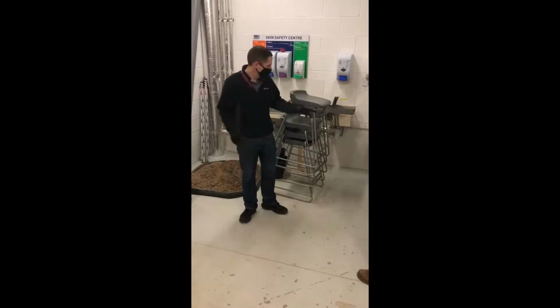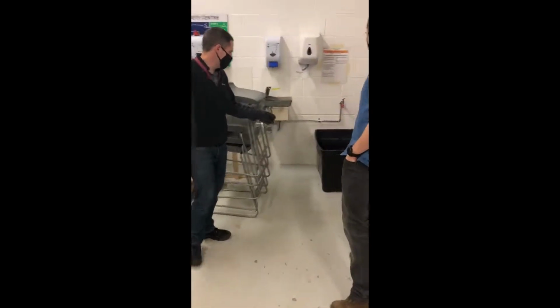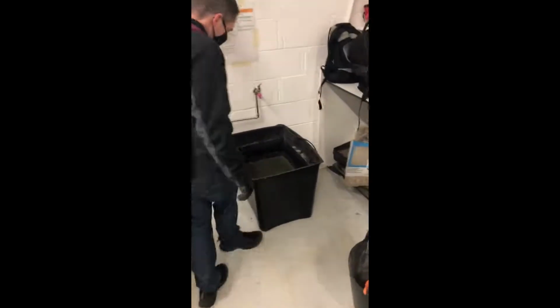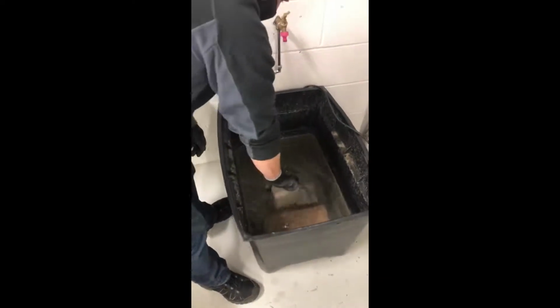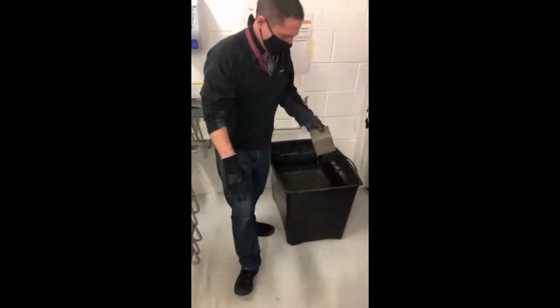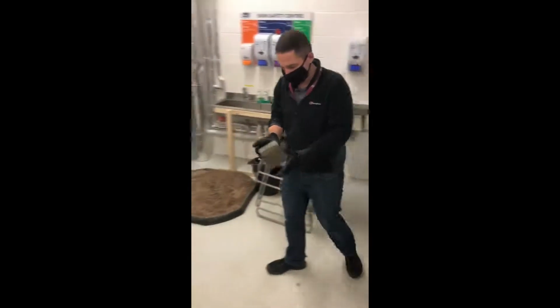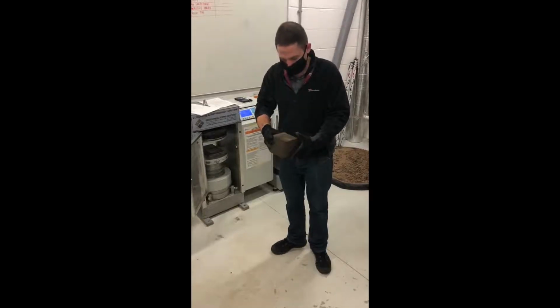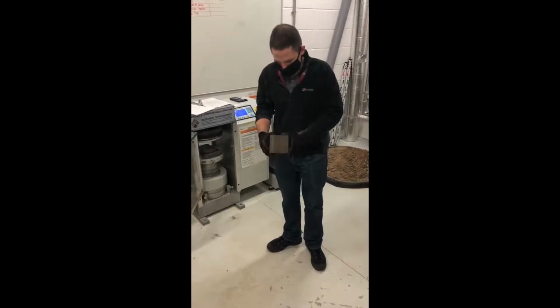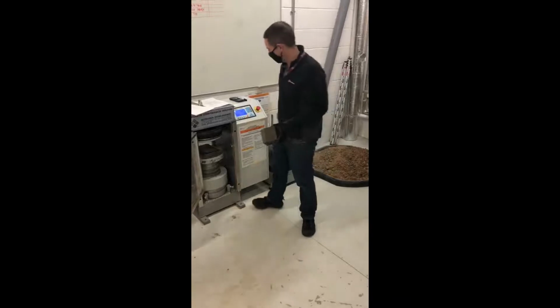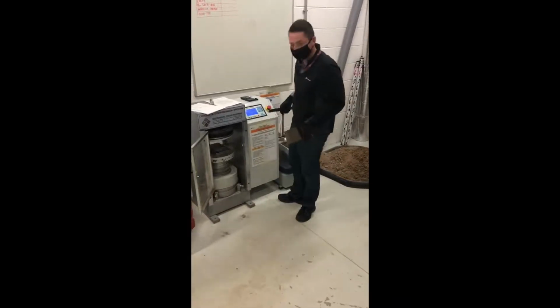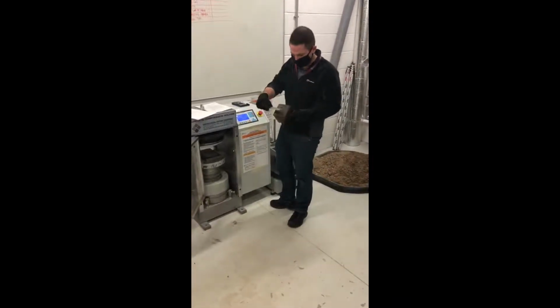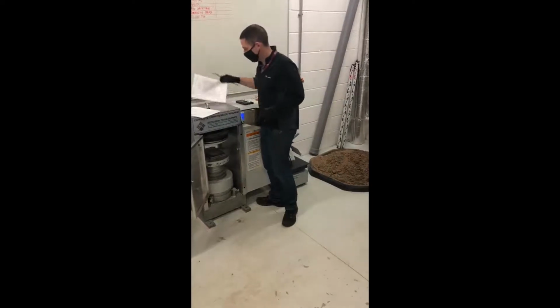So what we've got is the cubes. They've been in this curing tank now for 28 days. I've got two cubes here, so we'll start with the first one. Just looking at it, there's no major defects obvious from that sample. So we check the dimensions just to make sure there's no deviations from the standard.